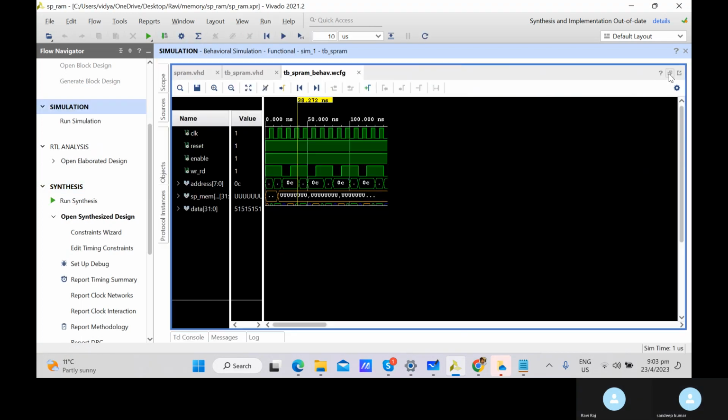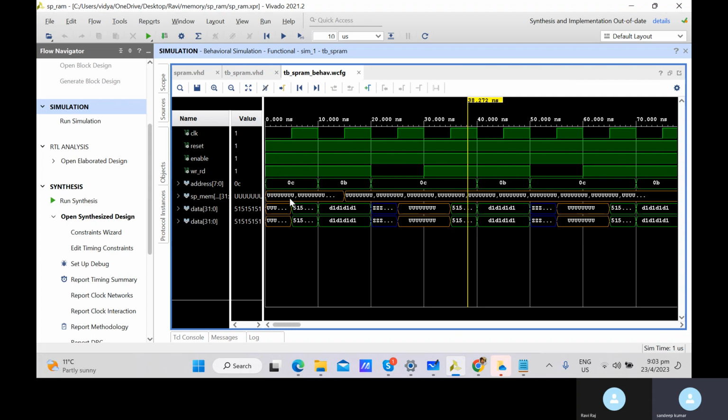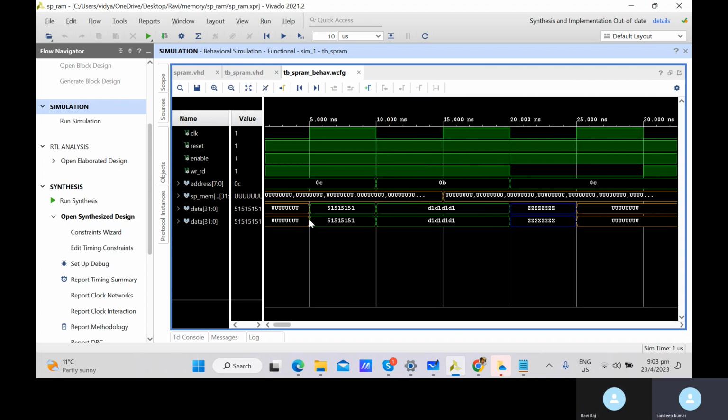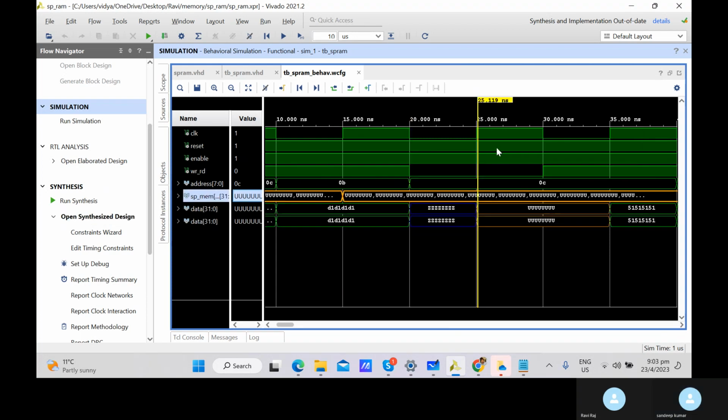You see? So this is a data port, right? Whenever writing, the write enable is there and write data is there, then it's a write. So you see, data port is driven by this. Else, data is changing. And what is the read condition? Read condition is when the enable is there and the read is there, write is 0. So this is the read side.